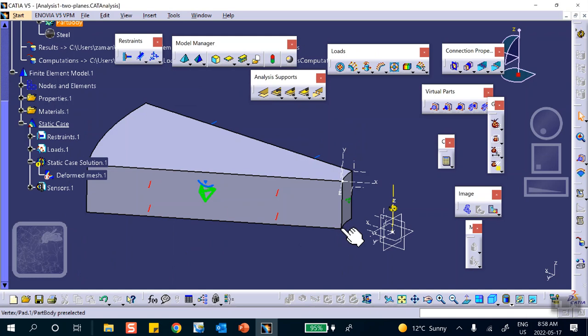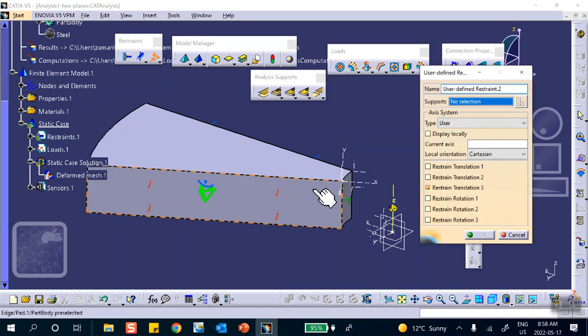So we take 1 point and say, hey, you can go up or down. So that is a user-defined restraint right there. 1 point. Now just be careful, because remember I used the user coordinate system. You may get lucky, but sometimes if you're not careful, up and down of the global coordinate system is different from up and down of the local coordinate system.